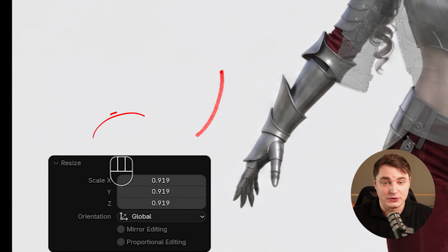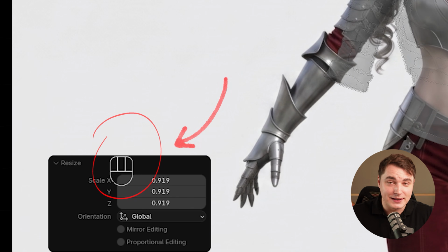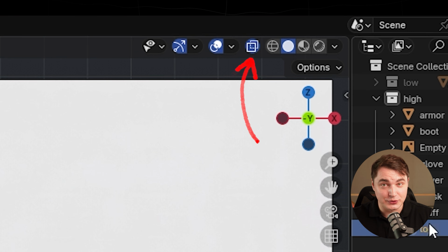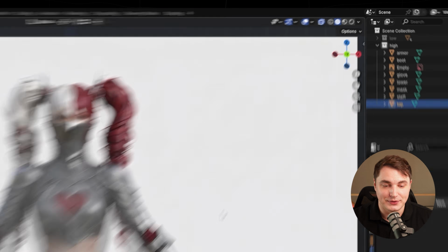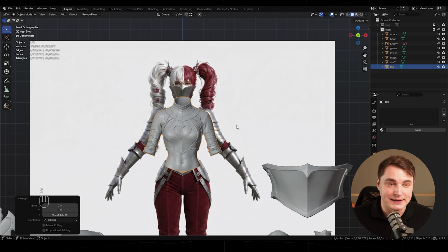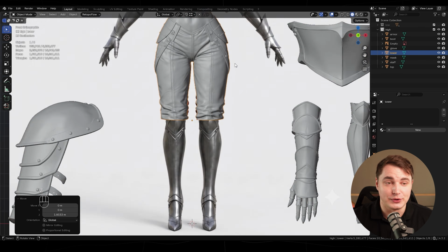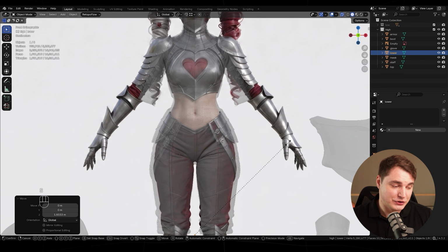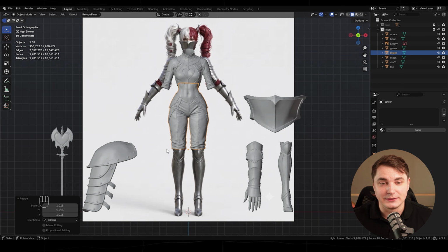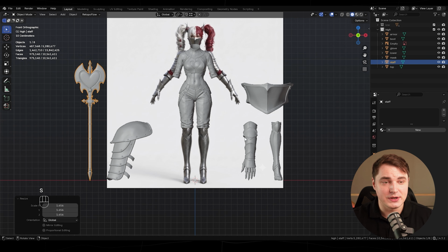And you can see most of the buttons that I'm pressing, and there is no big magic. First of all, a very useful mode is X-ray mode that allows you to precisely fit it according to the reference. Next, of course, are simple controls such as moving, rotating, and scaling. You can use the controls here, or you can use the hotkeys. G for moving around according to the camera, S for scale, R for rotation. So the first part seems easy.